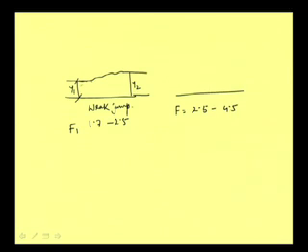Here this depth will be a little less than this one, y1. It is slightly decreasing. When depth is decreasing, then our Froude number is increasing, because Froude number is v by root over gy, and as you know, when depth is decreasing, velocity is increasing. Of course, for a particular discharge we are talking about.